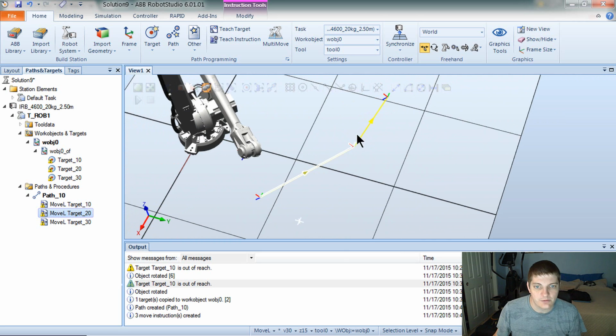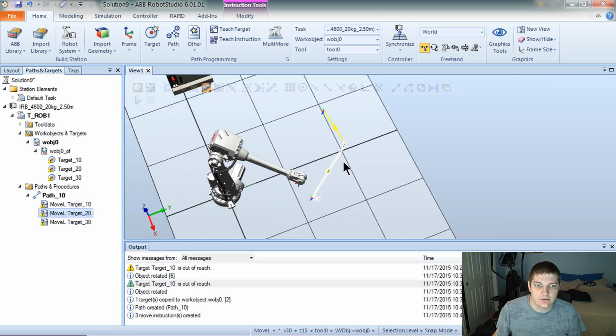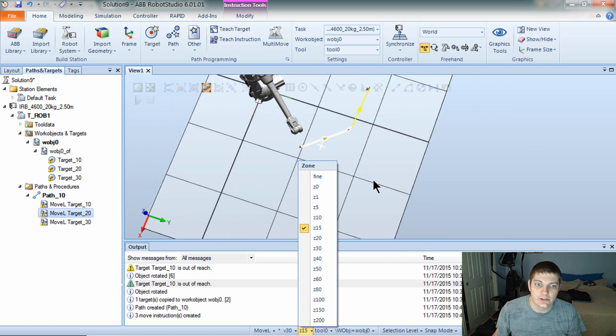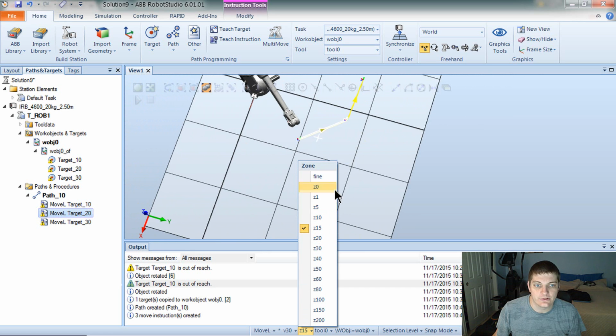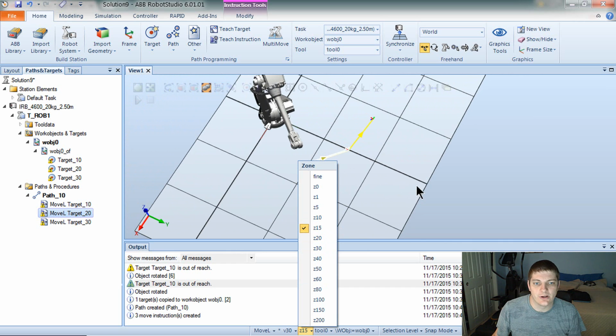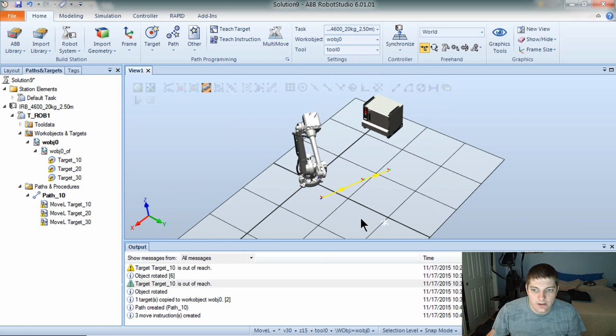But really, we want to just zoom right by this point. So essentially, if you set a high Z value, rather, it'll just swoop by generally in the area. If we have a smaller number, it'll go a lot closer. Z15 seems pretty good for general robot pathing points, or that's what I do. You start making it bigger if you have a lot of area around other objects and walls. You can really zoom through there to get your velocity up if you need to.